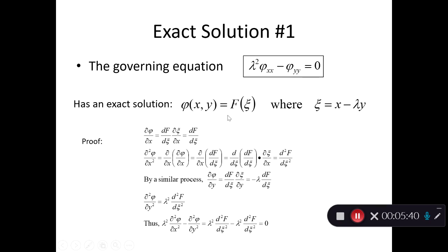So Ackeret's assumption that phi is constant along a Mach line is pretty valid. You may remember that in expansion fans we mentioned that along expansion fans, density is constant, pressure is constant, temperature is constant, Mach number is constant, and the Prandtl-Meyer function is constant. So in linearized flow, instead of an expansion fan, we just have Mach lines. So along Mach lines, phi is a constant.